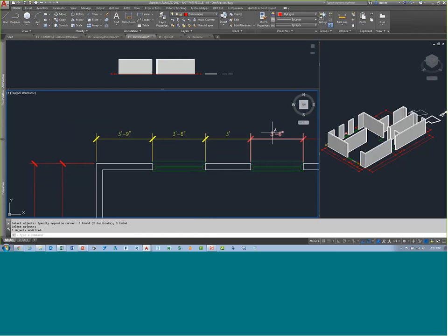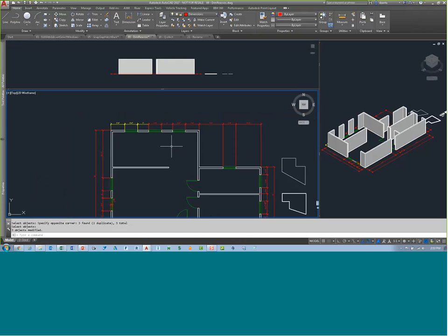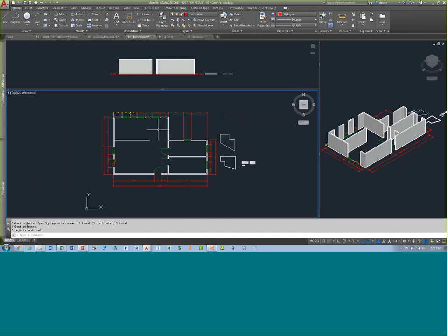And so this is kind of a neat tool for you to fix all the dimensions very quickly and easily. It's always wise never to override a dimension, by the way. And if you don't do that, you wouldn't have to worry about using this command. But from a BIM manager standpoint, it's a good way to double check to make sure anybody hasn't overridden any dimensions.